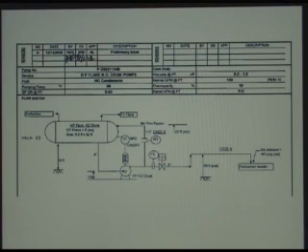It identifies the pipe size that goes to the inlet, shown that it's a gravity-fed system. We don't see any jumps, but that's the piping layout guy's job to make sure that doesn't happen. It's a motor-driven pump, and the control is level control based on a high level to low level inside the drum. The drum is an atmospheric drum, so there's no pressure inside, which will help develop pressure at the pump suction. It's vented off to the flare, which is basically atmospheric, which is why the design pressure is 0 psig. Gives you a size.